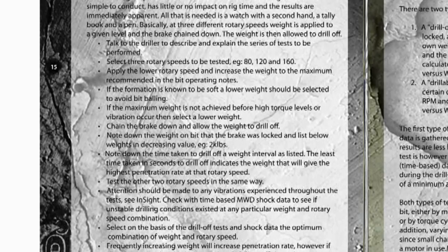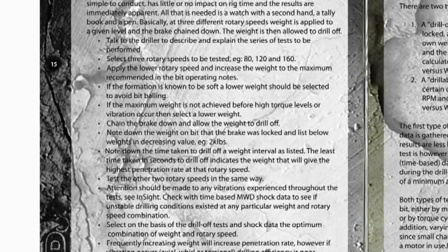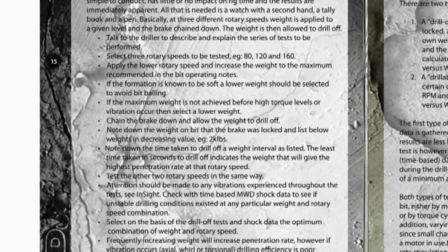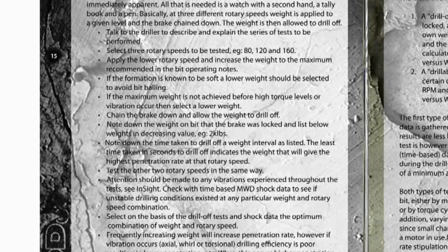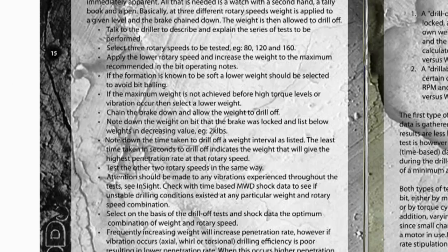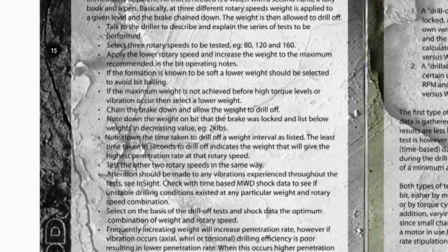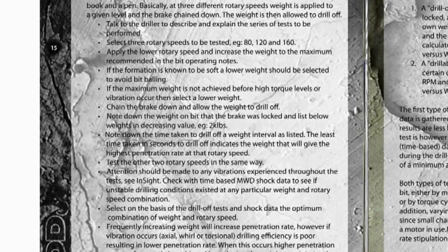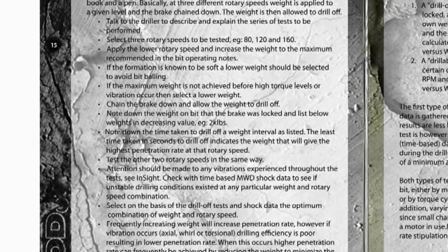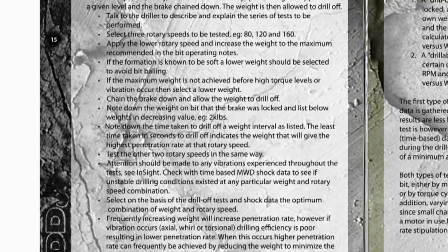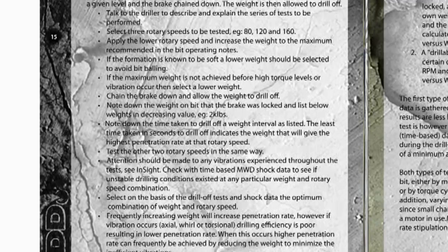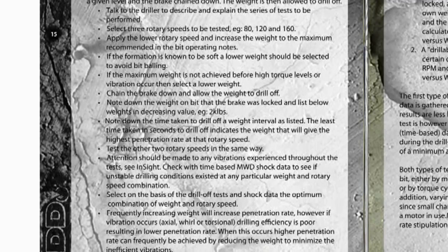Attention should be made to any vibrations experienced throughout the tests. See Insight. Check with time-based MWD shock data to see if unstable drilling conditions existed at any particular weight and rotary speed combination. Select on the basis of the drill-off tests and shock data the optimum combination of weight and rotary speed. Frequently increasing weight will increase penetration rate.